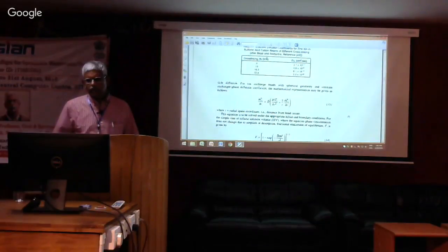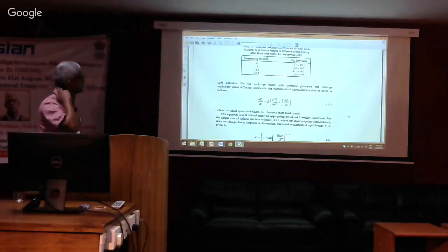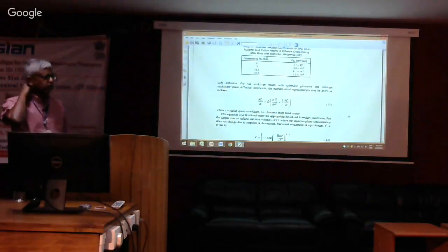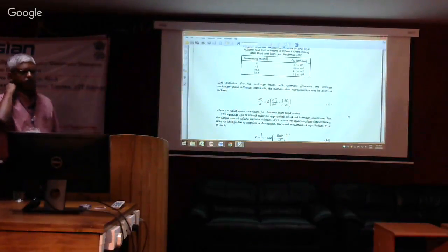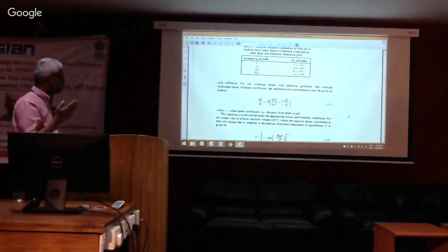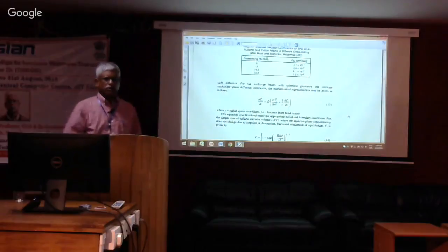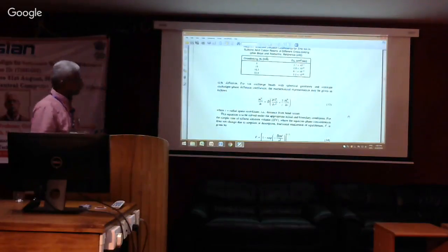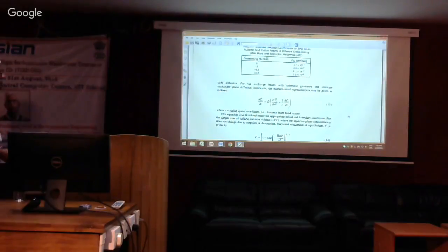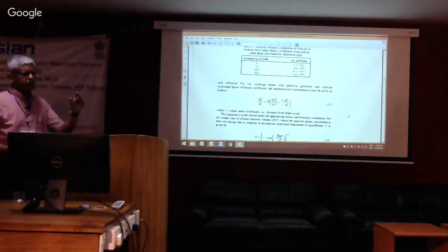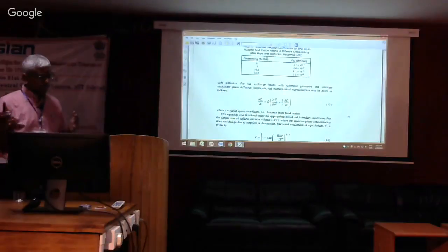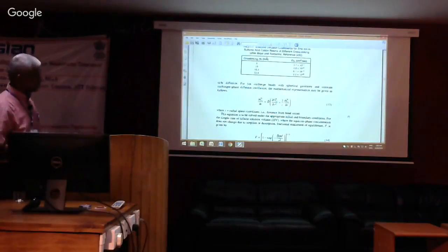And how do we get these diffusion coefficient values? It's a very classic partial differential equation, which I'm sure you have seen and done. This is the same model which we use for adsorption as well, interparticle diffusion. And there is this very famous book, Mathematics of Diffusion by Crank, and it has all the analytical solutions.